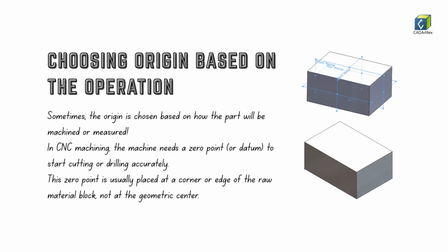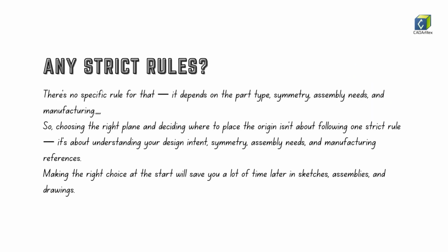Also, sometimes the origin is chosen on the basis of how the part will be machined or measured. For example, in CNC machining, the machine needs a zero point to start cutting or drilling accurately. This zero point is usually placed at the corner or the edge of the raw material block, not at the geometric center. So there is no specific rule for that.